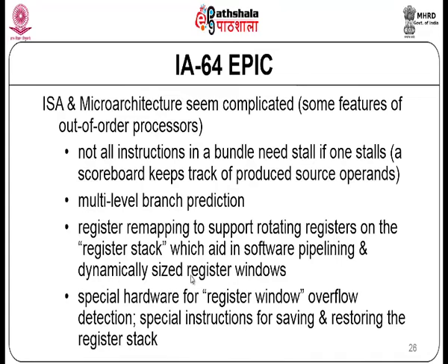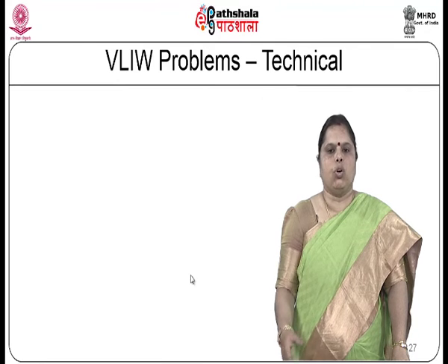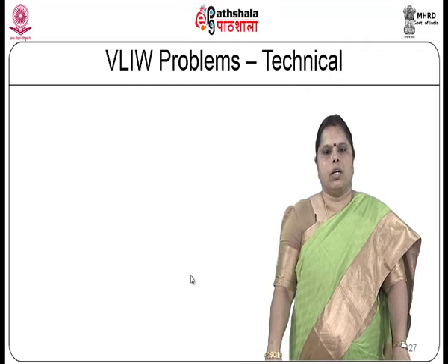You also have special hardware for register window overflow detection, and special instructions for saving and restoring the register stack. So all these are some of the features present in the microarchitecture of your IA64 architecture, which follows the VLIW style of architectures.